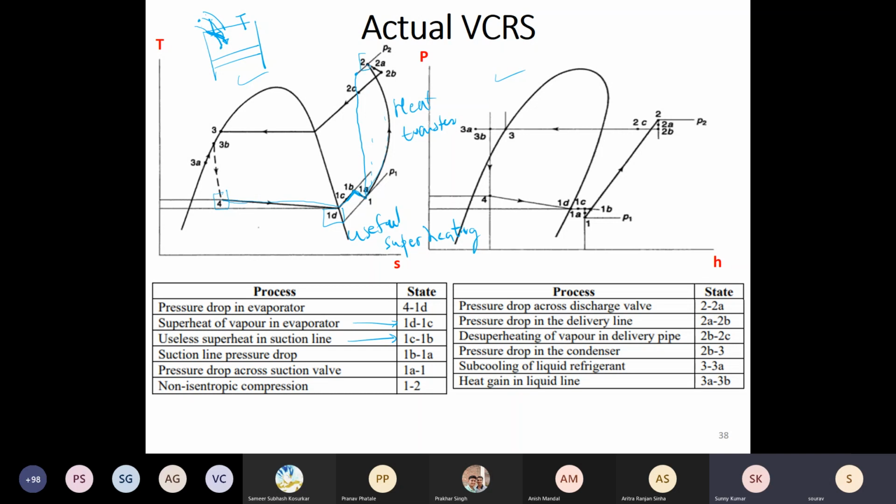And then this is, let's say, the exit or the discharge from the compressor. Again, when it comes out of the compressor, it has to push the valve up and then come off. So there will be some pressure drop as it flows across it. Again, there is a pipeline connecting all the way. There is also a muffler placed. In case of a reciprocating compressor, we have to reduce the noise.